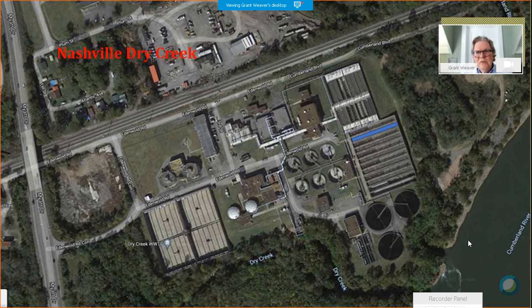Well, during the study, in one of the trains, we were trying to improve nitrogen removal. We did that by taking that whole aeration zone, the U-shaped tank, one train, so it heads to the right and then turns around and comes back from right to left into that blue zone, and they cycled the air on and off.